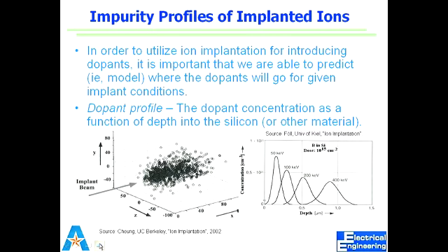To first order, we can approximate that the more voltage we use, the deeper the ions can go. But the deeper you want to send them, the more collisions they will face. So the concentration of dopants is something we have to compromise on. This shows boron in silicon at this dose.